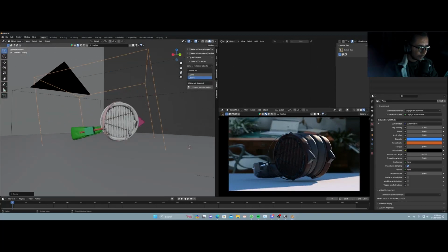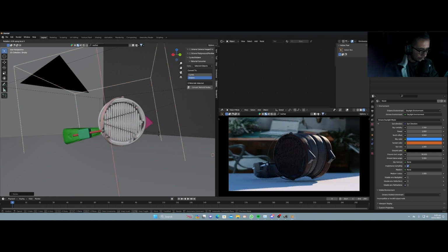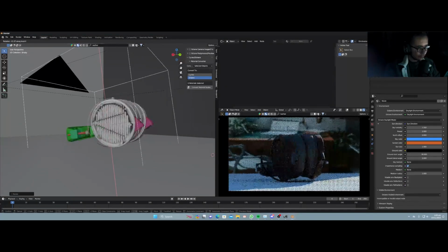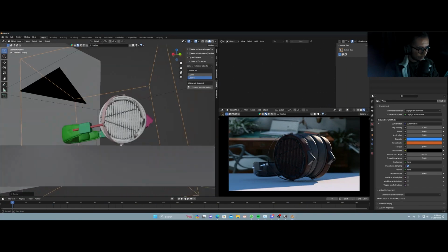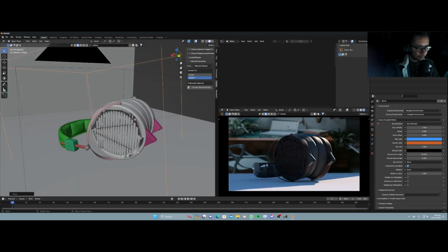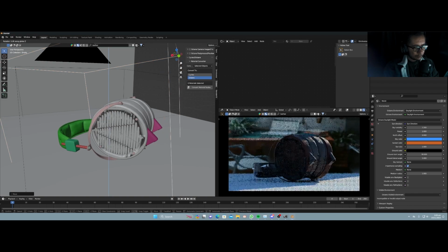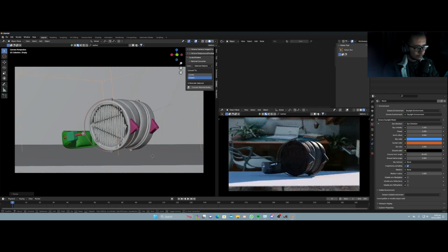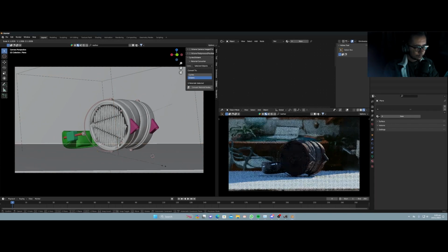Okay, it's still a bit up, so what I'm gonna be doing is, by the way, I'm using the local axes right now. And how can you access the local axes? If you want to rotate it on its local X, you press R and then double X. So this is the local axis of X. So I'll just put it down. Let's make sure it's not clipping. Alrighty, rotate it over here, come back over here to camera, just go out a bit,